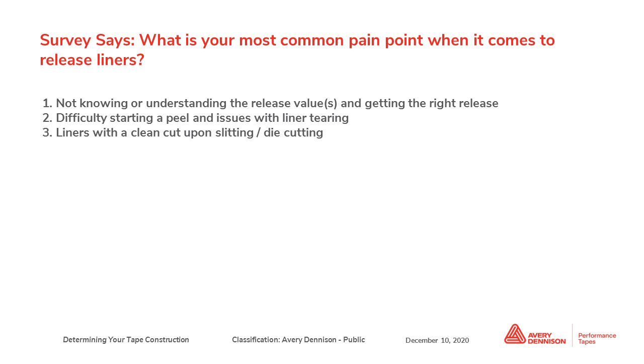Transfer tapes, as I mentioned before, to get the adhesive to remain properly on the right side of the liner, we have what we call a 3-to-1 release differential, where the force required to remove from the inside, where it's supposed to stay behind, is 3 times greater than the unwind of the roll. So that allows it to unwind nicely. For double-coated tapes, you generally want a 2-to-1 release ratio, but double-coated tapes have some forgiveness because you have that dimensional stability because of that carrier there.